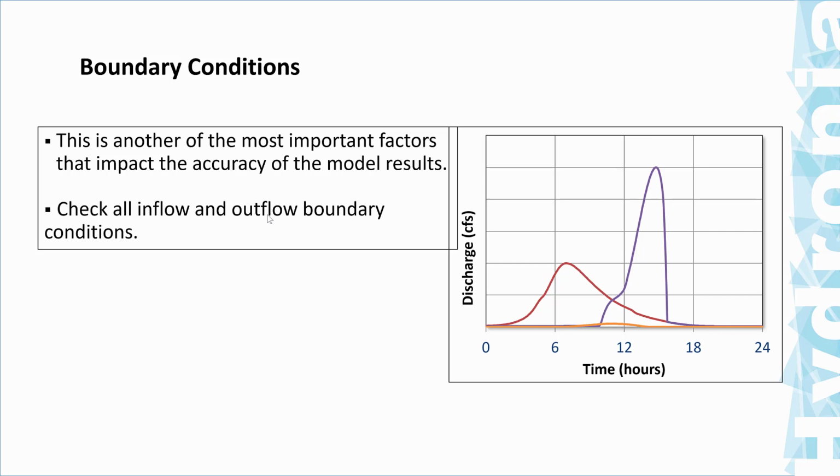So we need topography, we need to set a projection, and we need boundary conditions. What are boundary conditions? Well, boundary conditions are the data that we impose on the boundary at inflows and outflows to the mesh. So the boundary conditions are the ones that indicate the flow rate that comes from the river upstream, or how the flow behaves at the downstream condition.